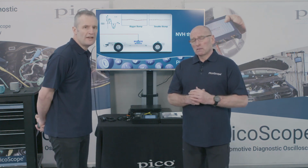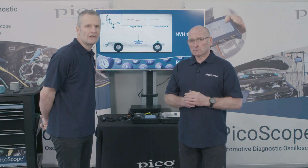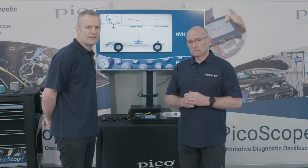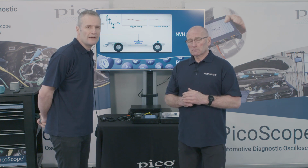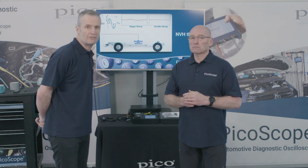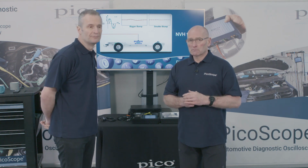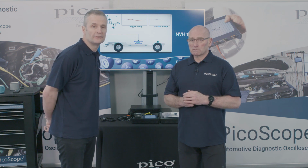Yeah, I think the effects of the vibration in the chassis are certainly... When we talk about vibration, it's something that we can feel. It's transmitting through the floor pan. It may be that the rear view mirror is vibrating at the same frequency as what we can feel in the floor pan. It's a visual representation of the same responding component.